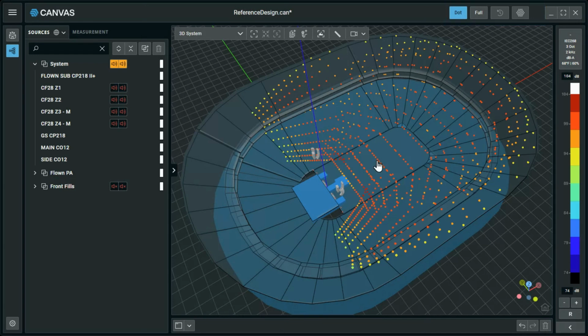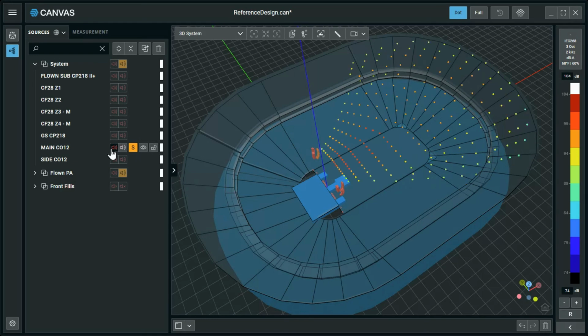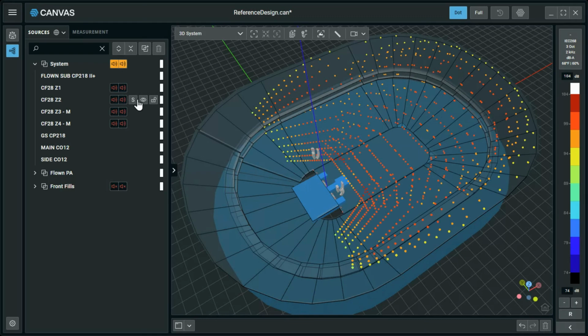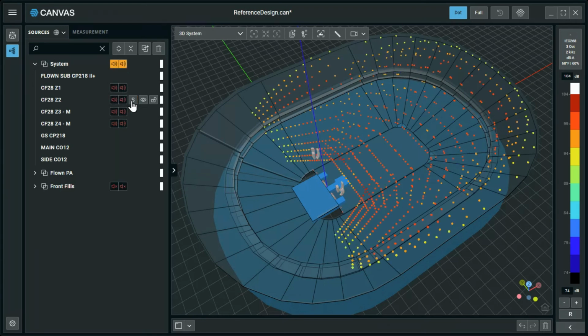With the dot mapping, a set of impact points is shown for every 5 degrees on axis within the stated horizontal coverage angle for each enclosure within a line array. This provides a quick visual of aiming and coverage for one or more arrays. For individual point sources, the dot map shows the nominal coverage angle, and the dot map is not used with subwoofers. Dot mapping is automatically recalculated as changes are made to the design.